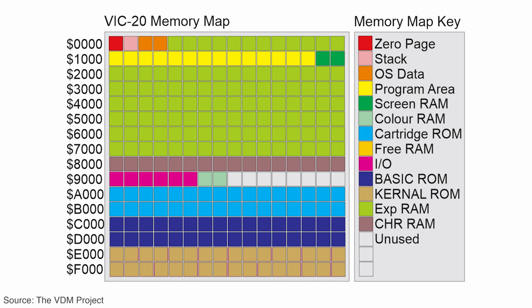Well, not quite. Here's a memory map of the VIC-20 as an example. The area in pink is the address range reserved for I/O, and it's only 4 kilobytes out of the possible 64 kilobytes that you get with a 16-bit addressing bus, and certainly on a VIC-20 with only 20 or 32 kilobytes of RAM total, it will work without a problem. We have lots of room to spare. But what if you want to have 64 kilobytes of RAM without giving up 4 kilobytes for I/O? That's when things start getting interesting.